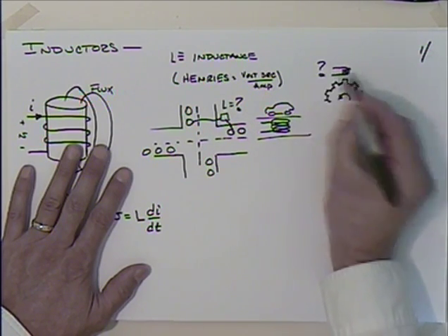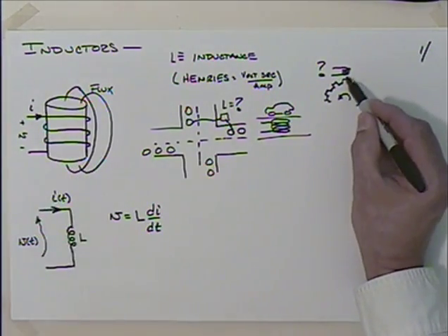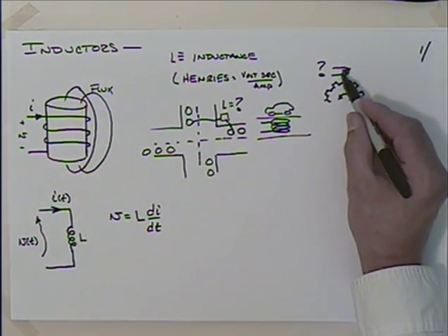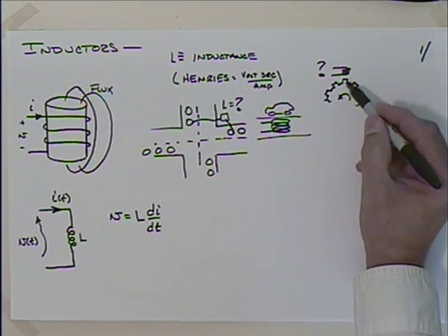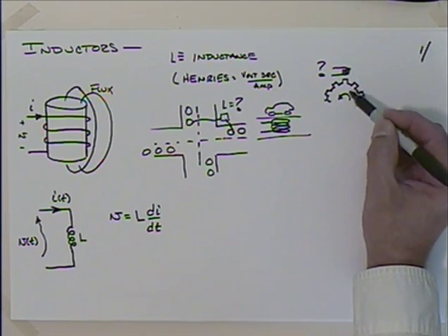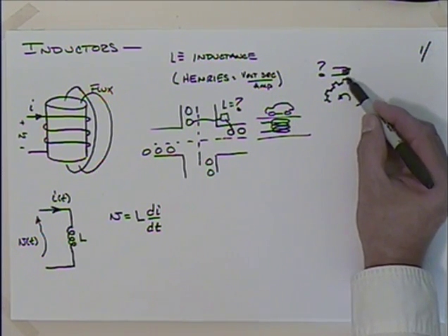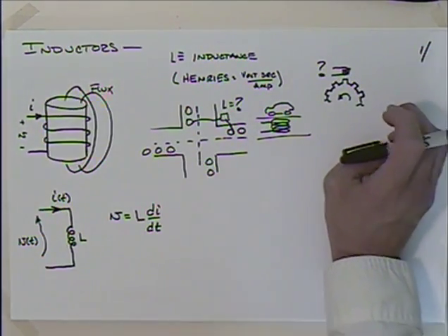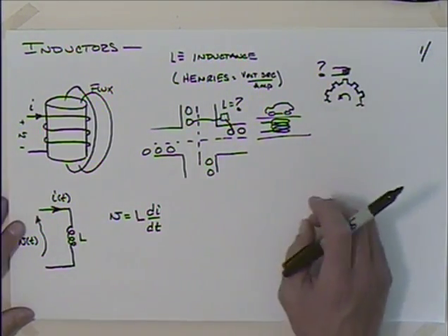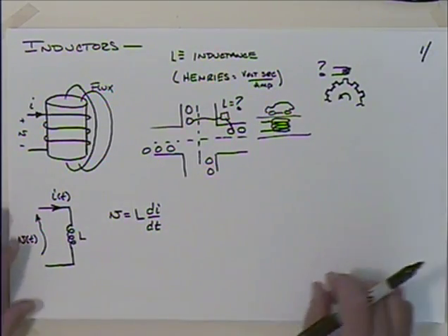and we query the inductance, and as this tooth comes around, it's going to change the inductance of that. So a lot of times if you have a crank position sensor or a tachometer or something like that in your automobile, it's probably using this type of technology. If you've got a spark ignition system, it's probably using this kind of technology to figure out where that engine's at and the timing of things in it.